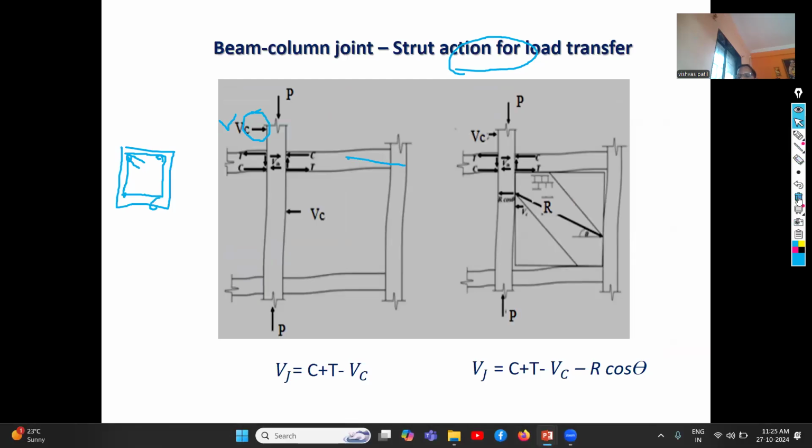Then the next element is called the beam column joint. The beam column joint during an earthquake behaves like a brittle element. It fails under brittle failure, and this is because of shear. So we have to assign the shear hinge at this particular junction.